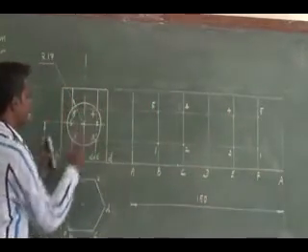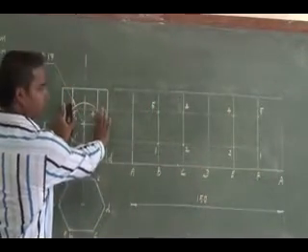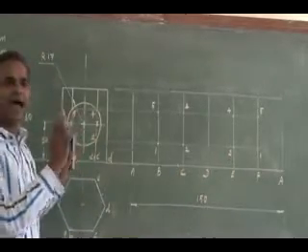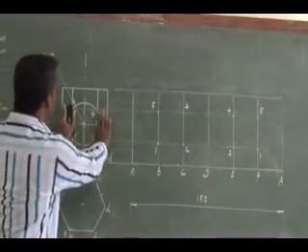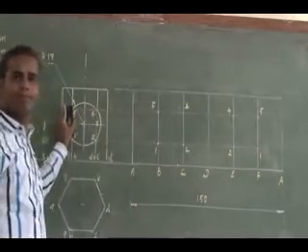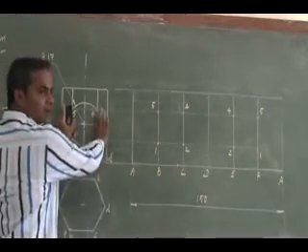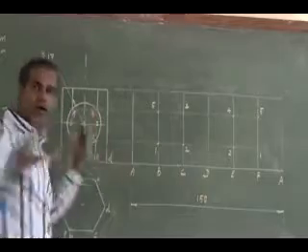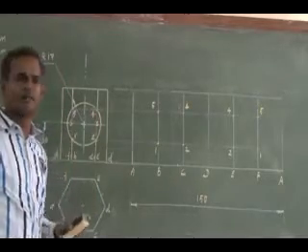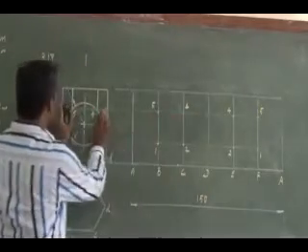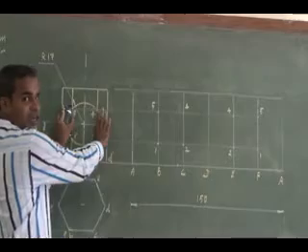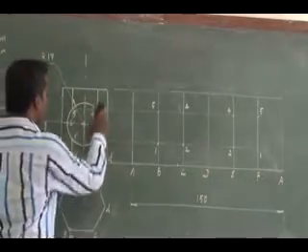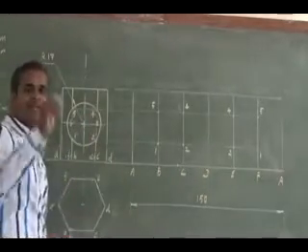Now look at this portion. It is on a flat face, a parallel face. How can I draw that on my development? Just this arc, I can draw it with a compass, in between 5 and 4 and 4 and 5. In this location, I can draw an arc of radius 17. So for that I have to mark the center.